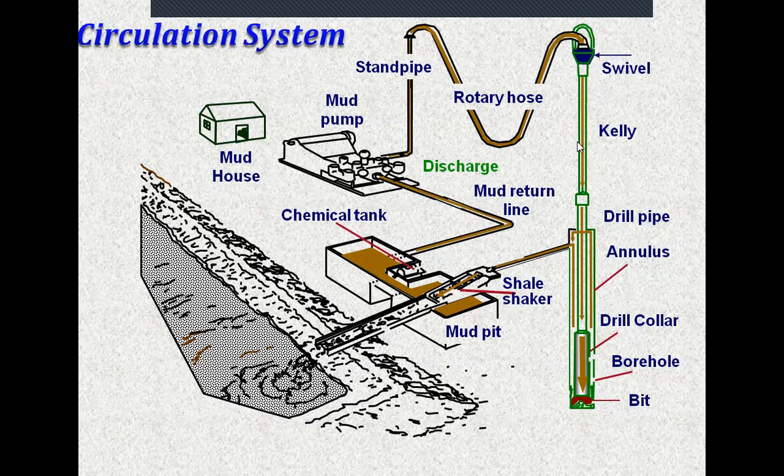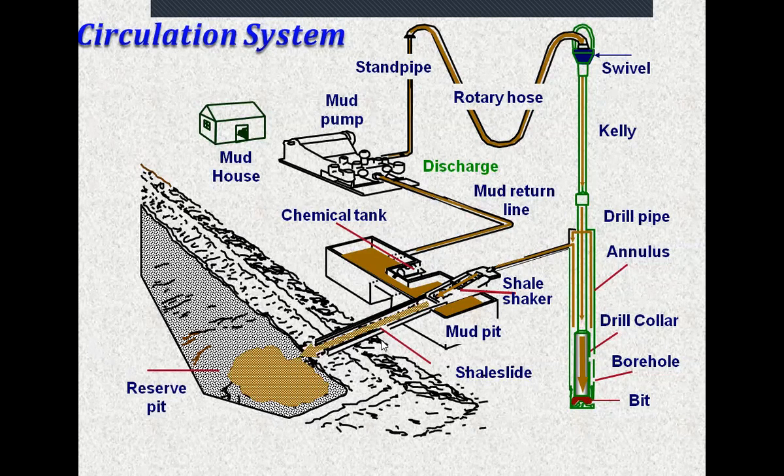So this is the full way of the mud from the mud tank through the mud pump, stand pipe, rotary hose, swivel, Kelly or top drive, the drill string, drill pipe, drill collar, then the bit itself, annulus, flow line, shale shaker for cleaning, and then back again to the tanks. And for sure, these solids are gathered in the waste bin.